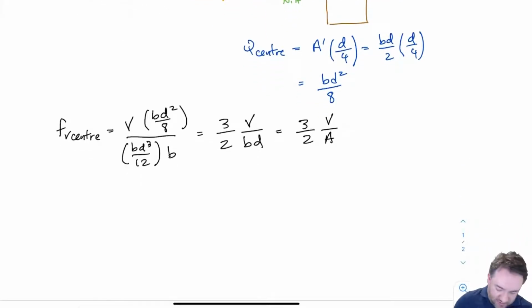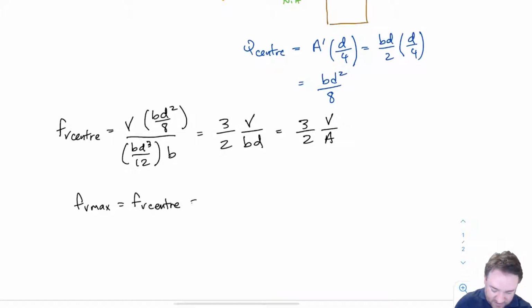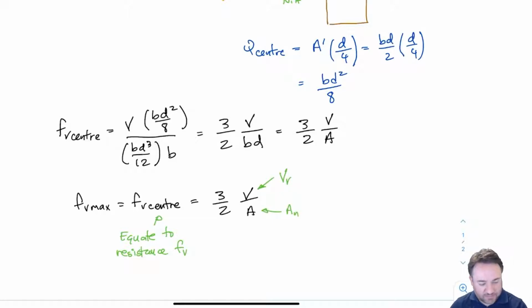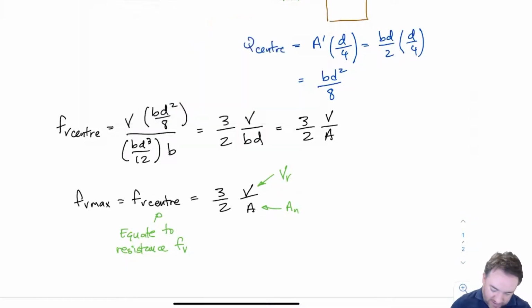Okay, so this FV center is also my FV max. So if I say FV max for a rectangle, my FV center, which is the stress at the center height, we have 3 over 2 times V over A. Now, if I rearrange this so that I equated this to resistance, so let's say that I have an FV, which is a strength. So I say I have a certain shear strength of X MPa. And then I can set my V to be my resistance because I'm trying to rearrange to find an equation for resistance in terms of force units. And my A, if I set that to my AN, which is my net section, then I rearrange, then I get...